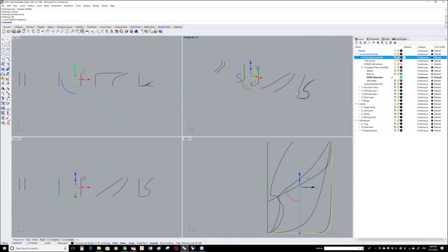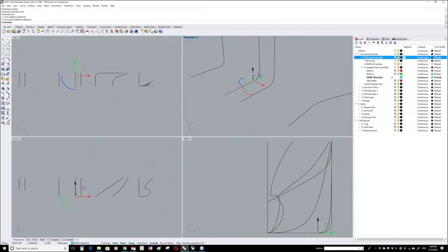One thing you see here already is that you see a straight line here. Well, if I move one of the curves, it's not a straight line anymore. And one very important basic rule about curves, but also about surfaces, is that when there are 3 points in one straight line, the curve will be going into straight. So 1, 2, 3, and from here on it is straight. 1, 2, 3, and then it is straight.